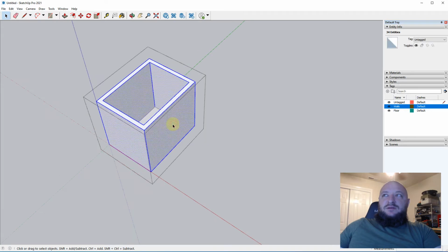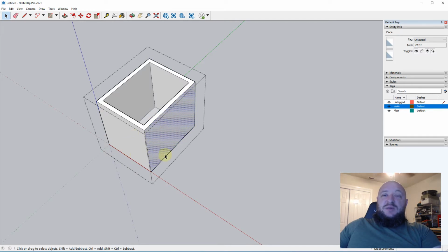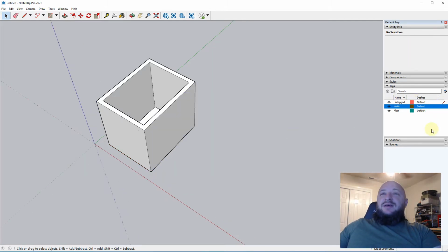Make sure, yeah, we're good. Okay. Always make sure you are working on the default layer and then grouping things or componenting them and then moving them off of the default layer as the component or group. Don't move individual raw surfaces and shapes to other layers, and don't work on other layers. Always remain on this default layer when you're working, because otherwise you can introduce problems in your model. That gets a little bit complicated later on as well, there's a weird situation where you might want to. Don't worry about it for this class. This is way beyond the scope for what you guys are doing. So just always make sure you work on that default layer and then group or component, move it off.